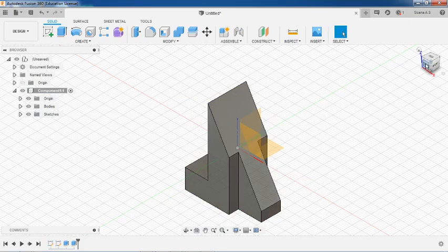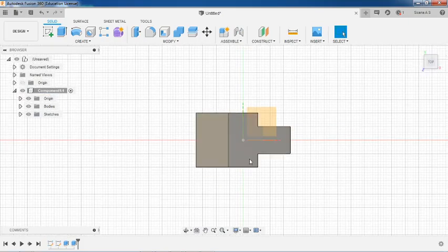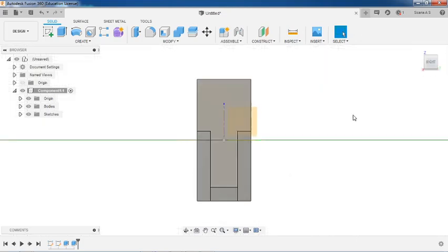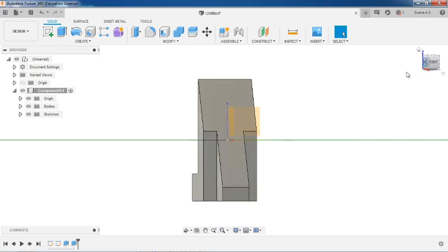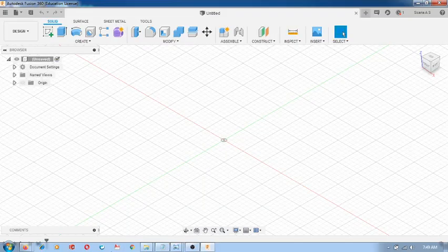Now check the front view. Front view should be like this. Then top view should be like this, right? So we have to draw one more view, I think you draw the right side view and place the view here. Only thing is that one hidden line will come, so you have to take care about this hidden line, that's all. So let us do the next exercise.